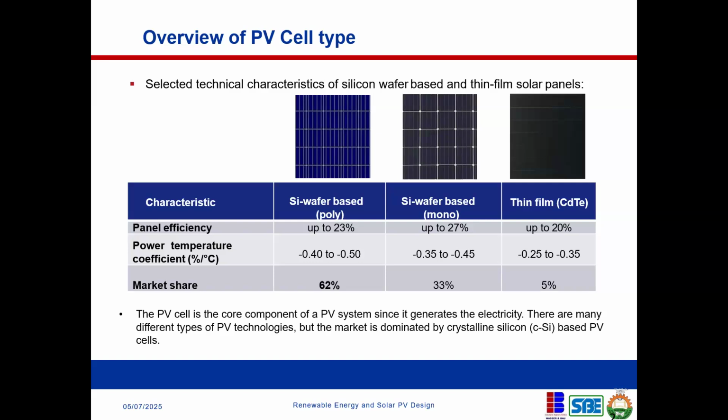As we proceed on this course, you will see how weather temperature affects the output of PV modules. When you have a high weather temperature, it reduces the output from your PV module. We're going to see that as we proceed in this course. But before we get to that point, just understand that one of the advantages of thin film modules is that they have high tolerance for high temperature, whereas polycrystalline and monocrystalline have a lesser tolerance.